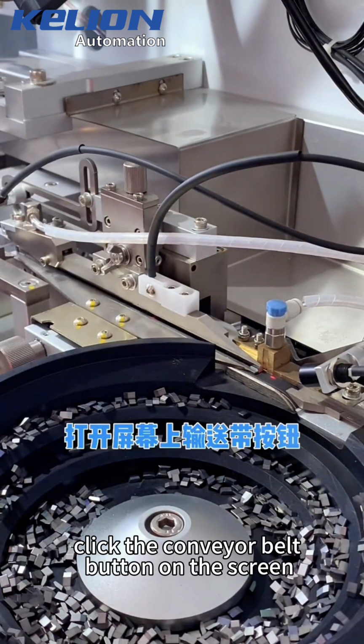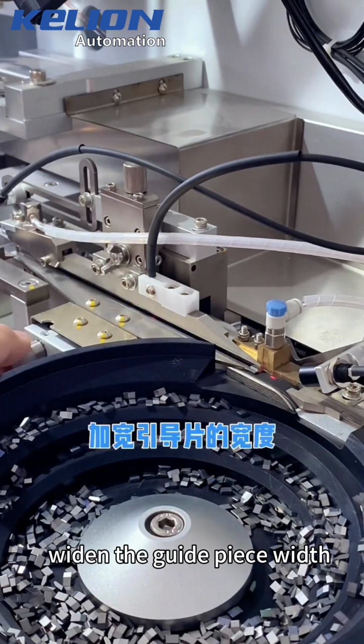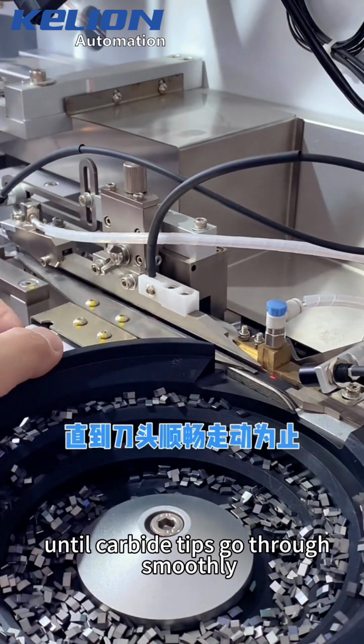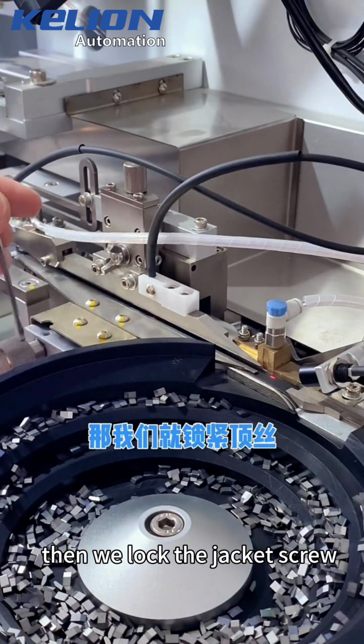Click the conveyor belt button on the screen. The conveyor belt opens. If the carbide tip is stuck, widen the guide piece width until carbide tips go through smoothly. If carbide tips smoothly go from the tail to the front, then we lock the jacket screw.